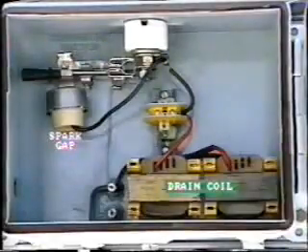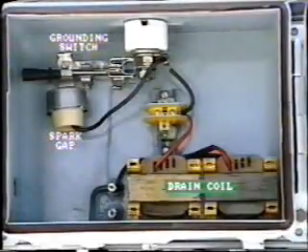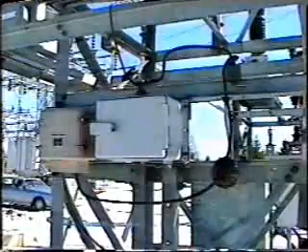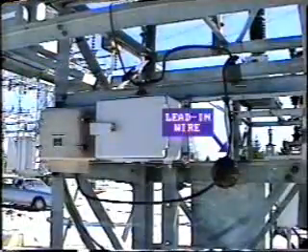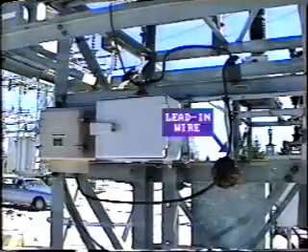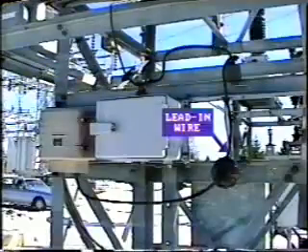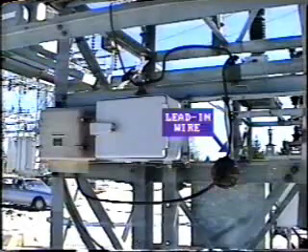First, close the grounding switch, then check the connections inside the unit. Coming down from the base of the coupling capacitor, you should see a single insulated conductor called the lead-in wire. Though this is normally a low-voltage connection, it could rise to line potential if the drain coil fails. The lead-in wire may be supported on insulators or run in PVC conduit. It may even be run in metallic conduit, but this is not good practice, as the capacitance of the wire to ground will be larger in metallic conduit, and this extra capacitance could affect the tuning action of the LMU.